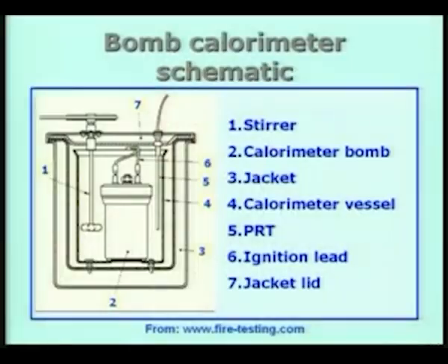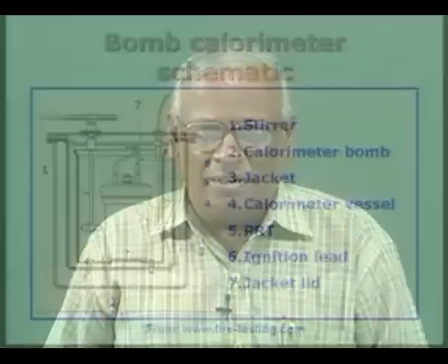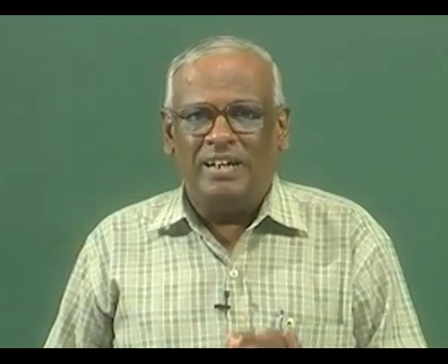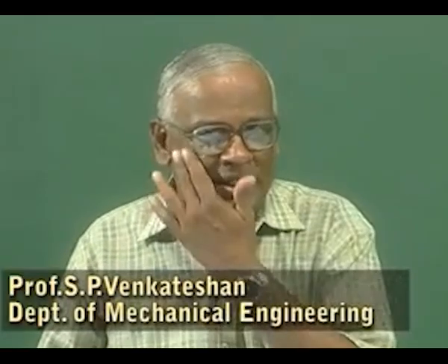we had. So, in this case, during the process of combustion, a certain amount of internal energy has been released by the combustion process. Because of this, the temperature of the calorimeter goes up, and if we know the calorific value or heating value of the fuel, in this case benzoic acid, I can use this as a calibration experiment to find out the capital C for the calorimeter. You remember the calorimeter we used earlier had a capital C, which is the mass specific heat product for the calorimeter. So, the first experiment using benzoic acid as a standard material is to determine the constant C for